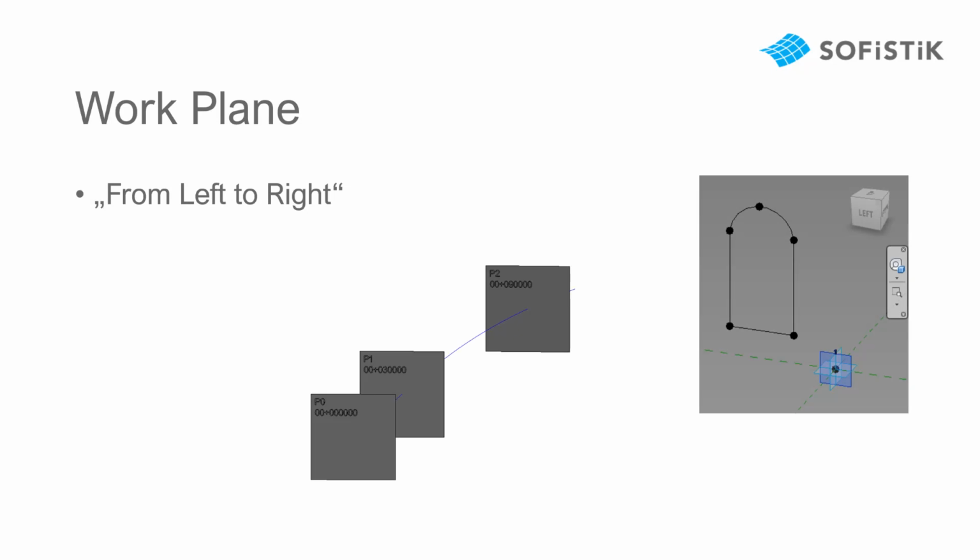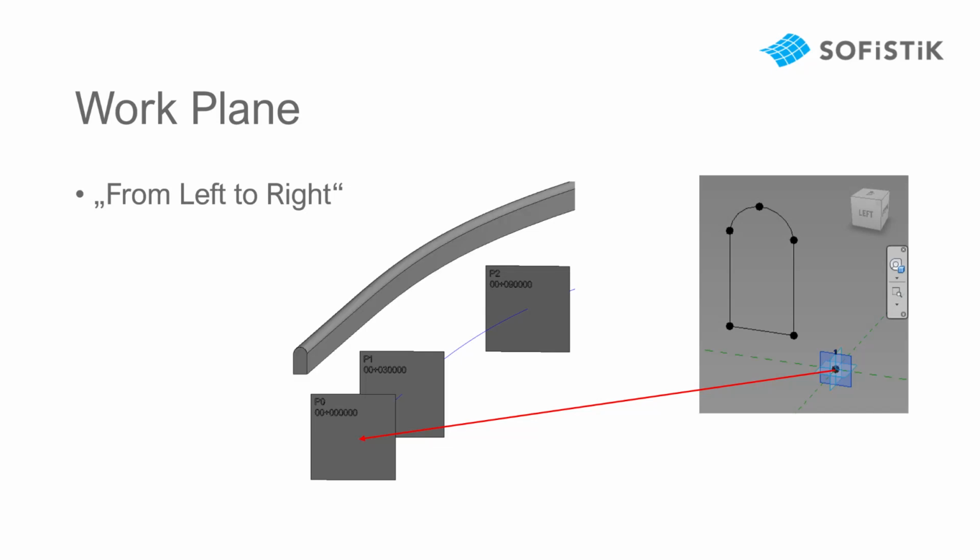When we now take this family and place it via the superstructure command, the way you have to imagine it is that we reference this adaptive point exactly to the origin of the inserted axis. The way you can imagine it is that the two-dimensional reference is placed in an interval along the axis, which is then swept along the alignment of the axis.